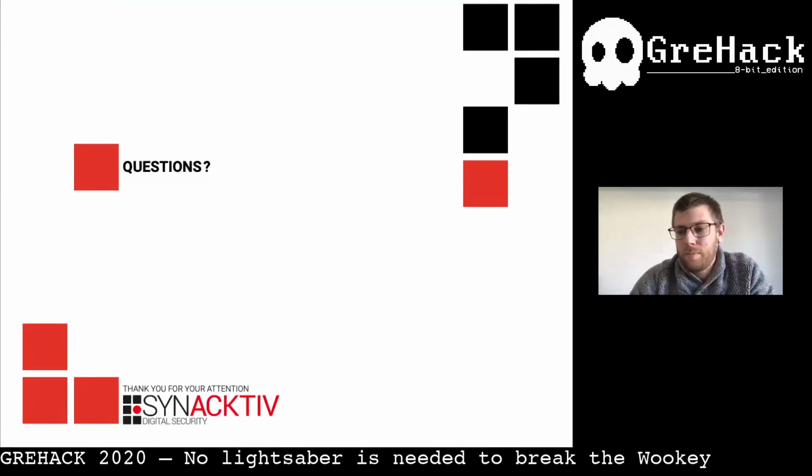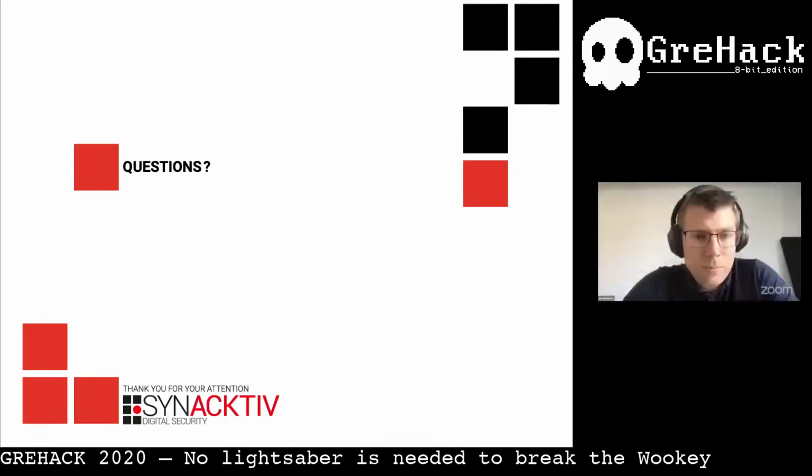Thanks, David, for the talk. So we have some questions that have been asked in the IRC channel. The first one is, your glitch on the VDD works, but did you try on the CLK? No, we only tried power fault injection because there is some public research on that method, and we know that it can work.